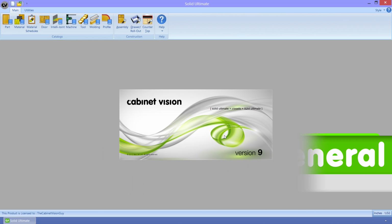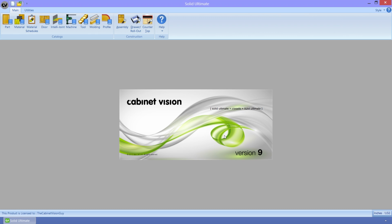Version 9 has a whole slew of general features that have been added throughout the program. Let's go through those now. First, I can show you here at the splash screen that the unit type and precision buttons have been simplified quite a bit. First off, all we have to do is click on the unit type and it will change to the other type. Next, when we click on the precision, a menu will pop up allowing us to select the various precisions for that available type.